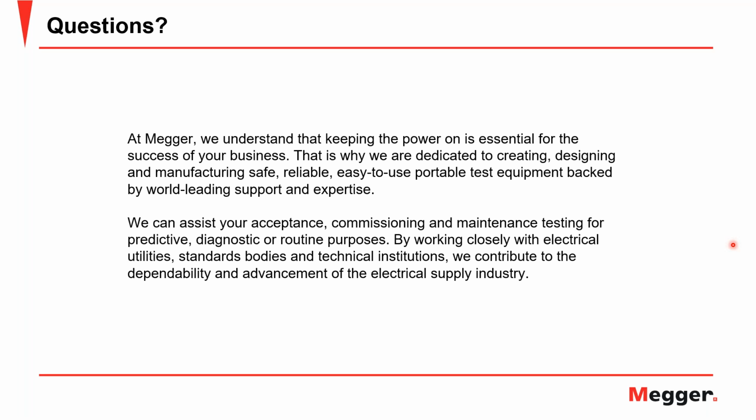So negative sequence, or symmetrical components in general, it's a mathematical tool. There's no real physical interpretation. I guess with zero sequence, you could have an open delta voltage and a zero sequence CT, but it's still measuring the residual voltage and the residual current, which happen to be the zero sequence.